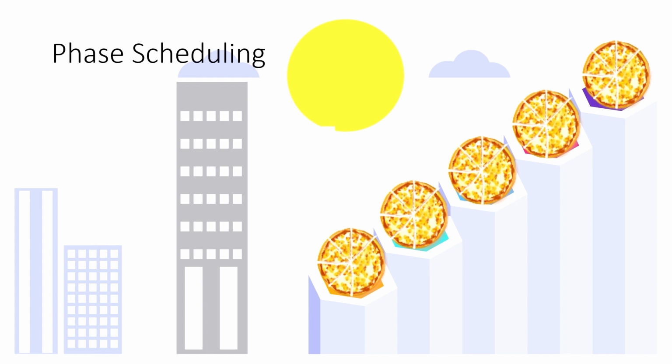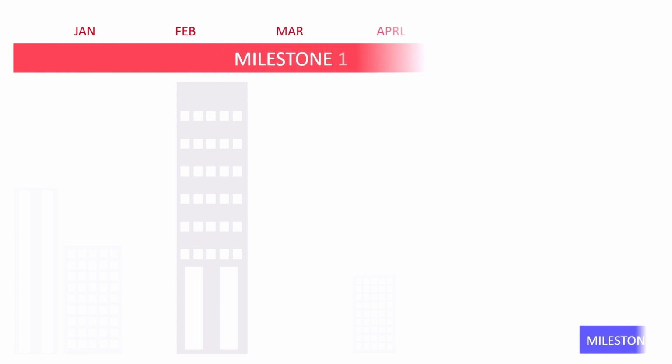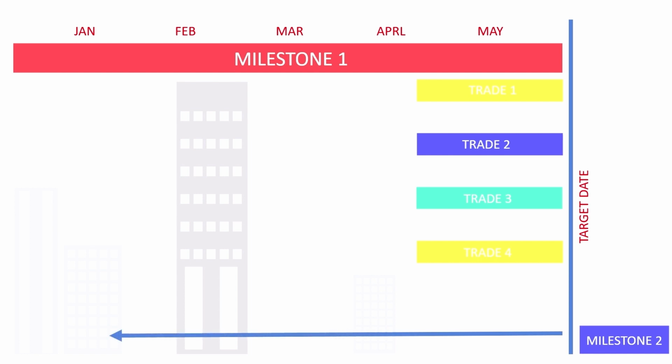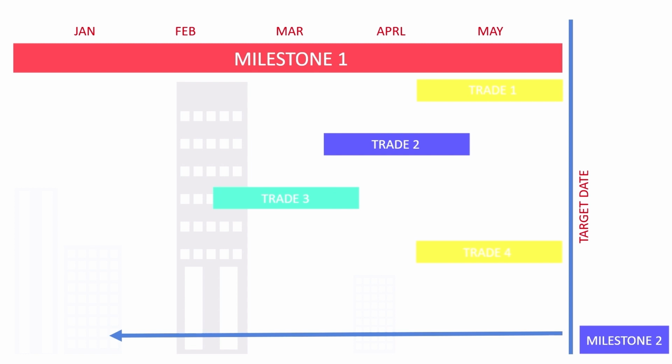To further the illustration, we take a target condition from the master schedule, identify the teams or trades involved, then the teams are gathered together. Identify the target date from the milestone and start working back. This is known as the pull technique, or sometimes called reverse phase scheduling, which results in the tasks being sequenced so that the completion of work receives a handoff.